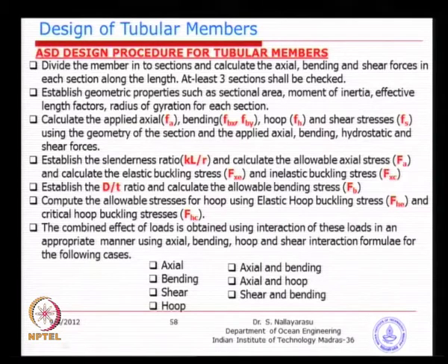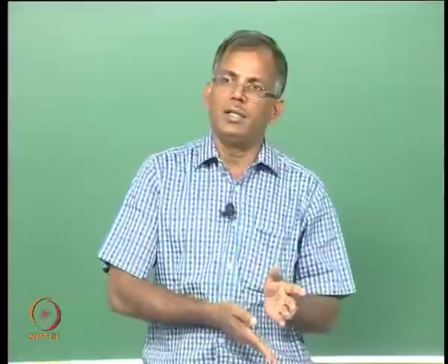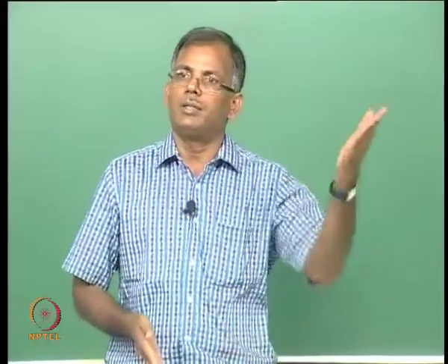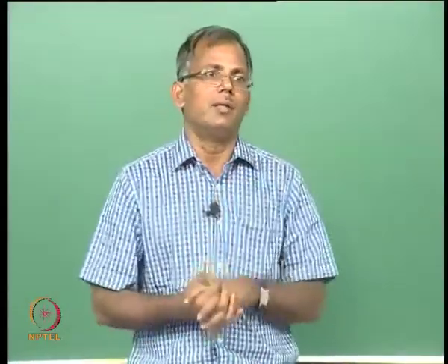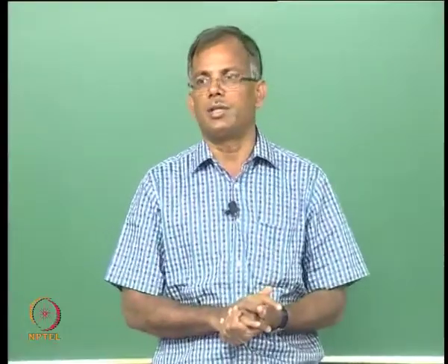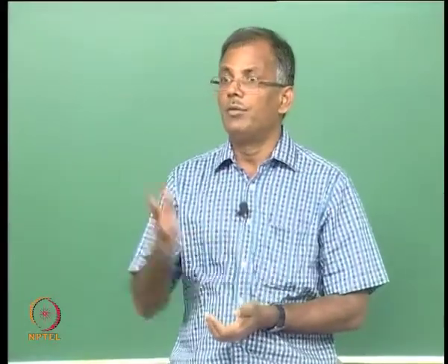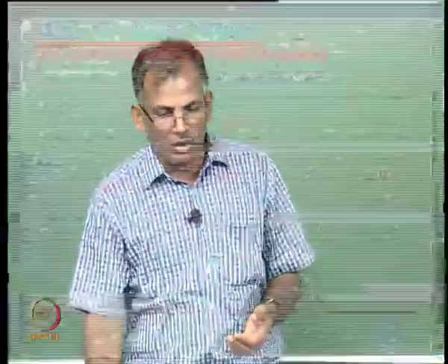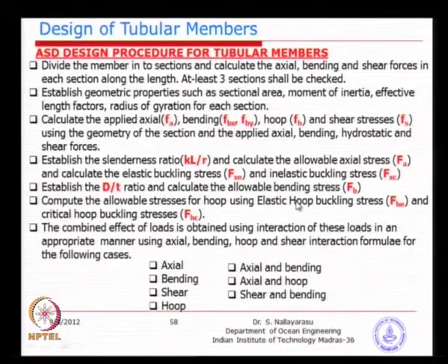Now, when you are calculating the allowable stress for the axial effect, you need to make sure that buckling is taken into account. That is what we learned earlier, whether yielding is governing or buckling is governing. As long as you have a cylinder member, buckling may actually make the structure fail before yielding starts. So, basically allowable buckling stress needs to be found in terms of reduction in the allowable stresses for